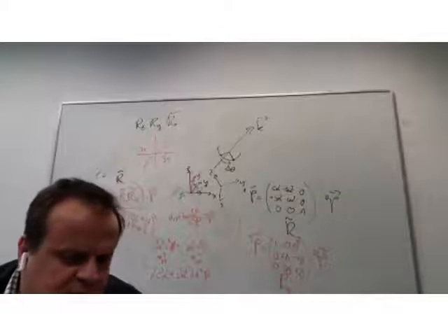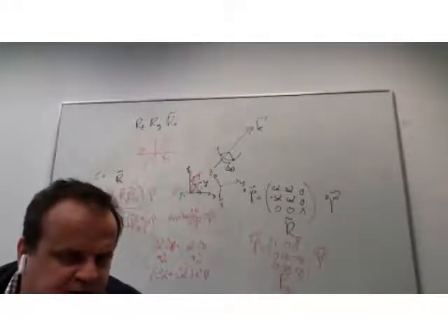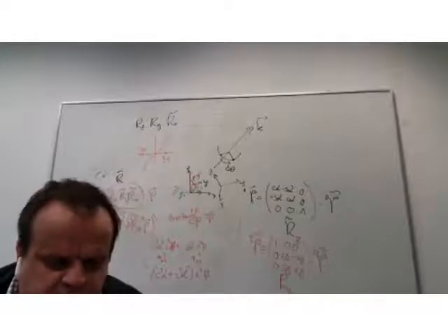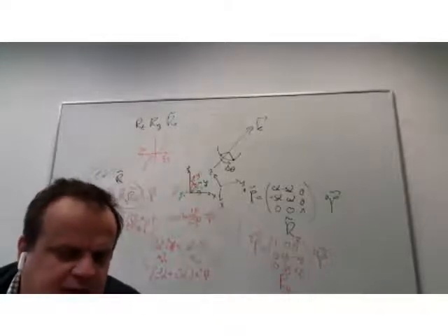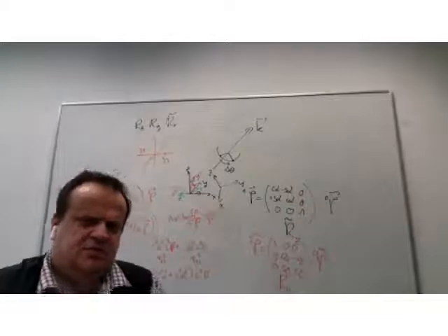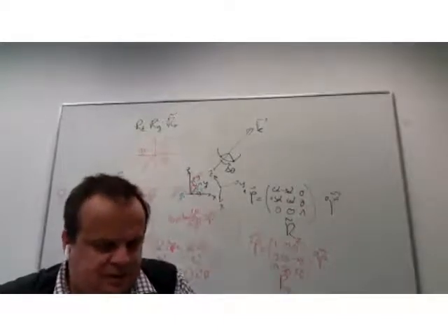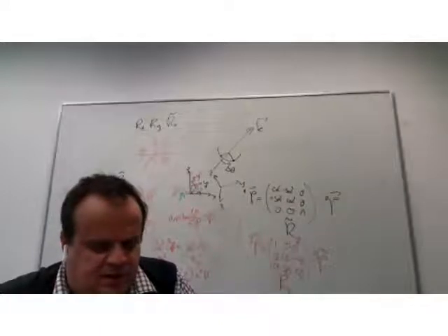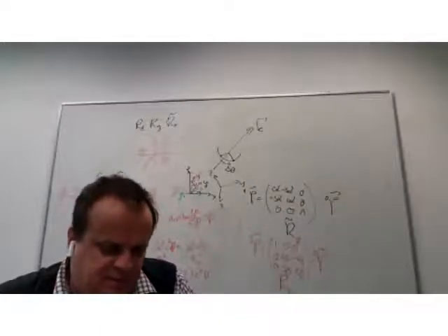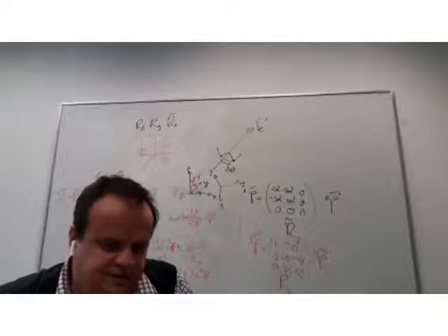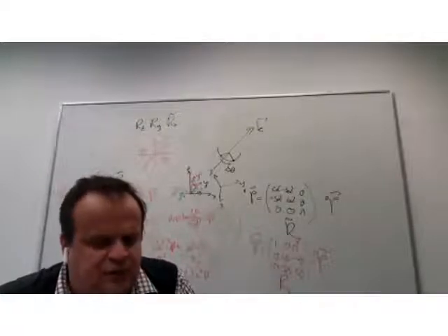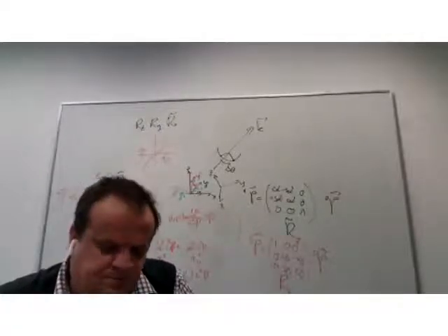So now, if your robot passes through beta equals 90, then the original x, y, z analysis of the rotation matrix would require you to do singularity checks all the time while decomposing the matrix. But you may choose one of these, if you have limited ranges of the angles, to find a better explanation of what's happening.